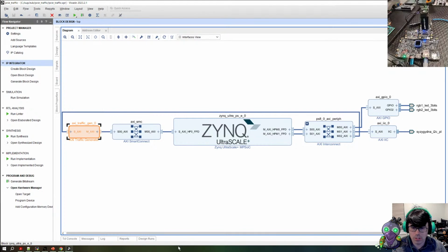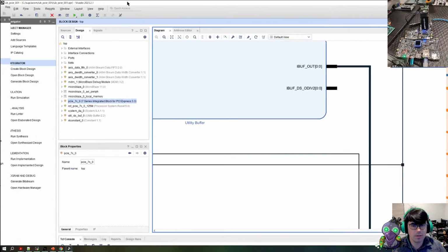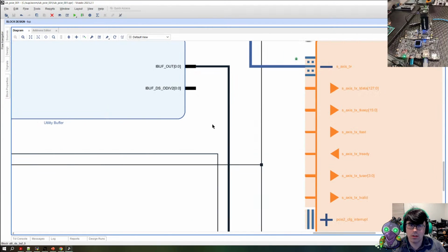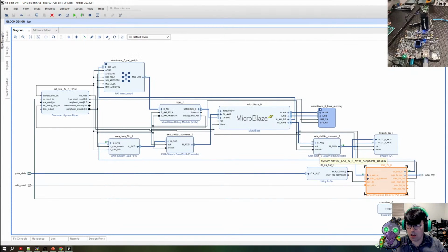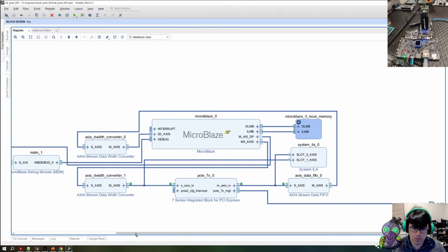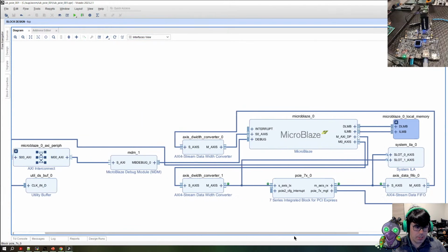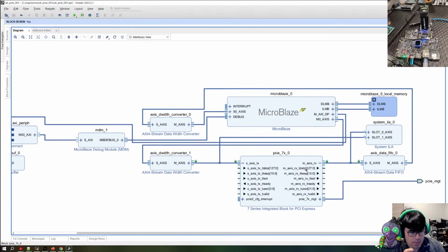Okay, so now this is our root complex. Now let's look at the endpoint. Our endpoint is a software-defined TLP packet reader and generator. Let's go to interfaces, interface view. What's happening here is we have the basic block, and this is doing AXI stream input and output. These are just very basic TLP packets. We're not doing anything fancy with them, or the system is.